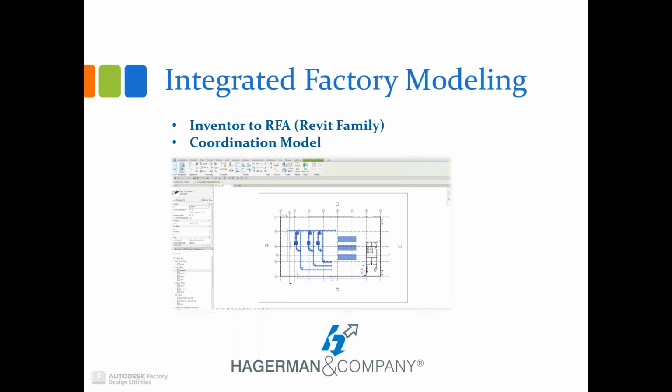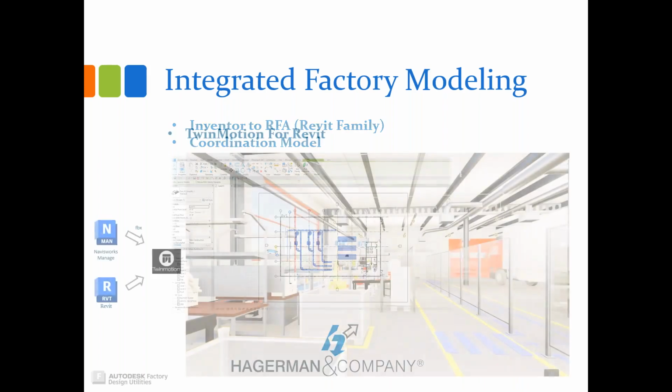And then the other option is you can take the actual Inventor file and open it in Navisworks. That will automatically create a cache model, which could be inserted into Revit as a coordination model. I'll show that option first in the demo, just because I don't think that option is as powerful as the Revit one. So we'll see both.